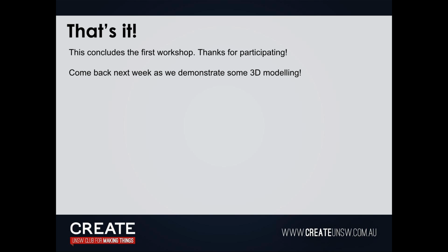So drawing from design, CAD practice, just call it that. I'm going to do carpal tunnel like this. Right. So drawing, create new, that's fine. Template from scratch. There are templates if you want. Standard ISO, that's fine. Units, millimeters, A3, A4, A2, A1, whatever, it doesn't matter. We'll just go with A4.